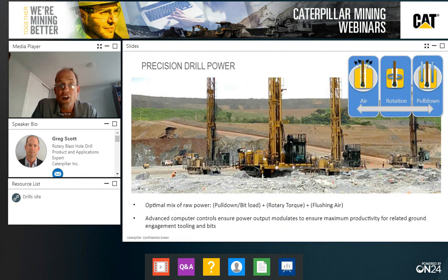Designed specifically for large quarries and mining operations, this medium class platform drill drives production. If it's quarry, contracting, or hard rock gold mining, we typically see this machine configured to drill 165 millimeter all the way out to 200 millimeter, 6 to 8 inch respectively, driving DTH hammers and bits. We also have some applications where we're pushing 216 to 228 millimeter, 8.5 to 9 inch bits with a larger class hammer.